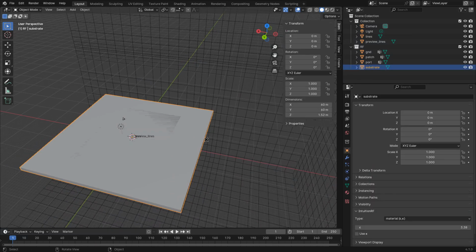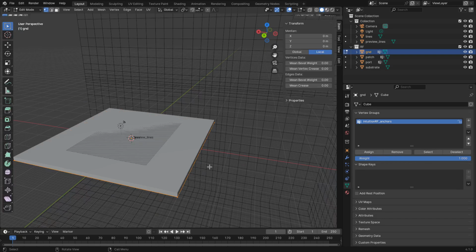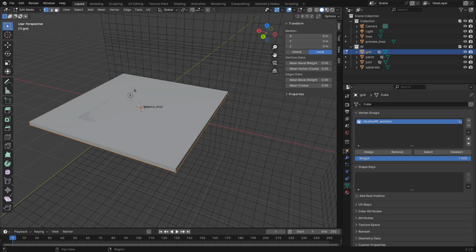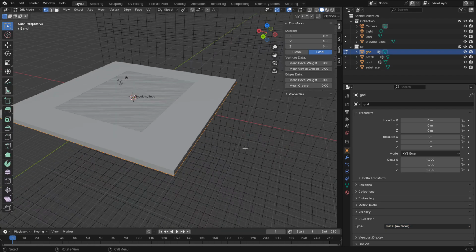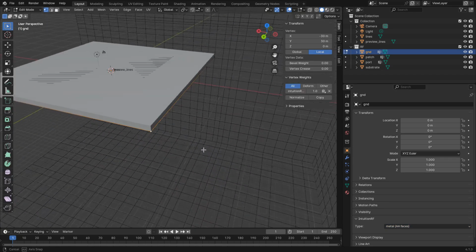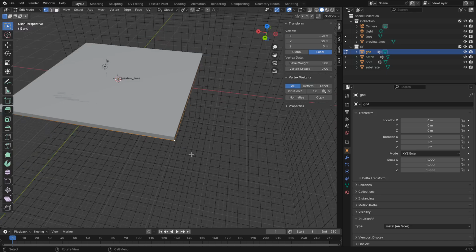So what we can do instead is add more anchors to the model. Because we are using axis-aligned faces, only faces in the model will be considered in the simulation, which means that we can add lines and vertices, floating vertices, that will be ignored in the simulation, but will act as anchors for our meshing.